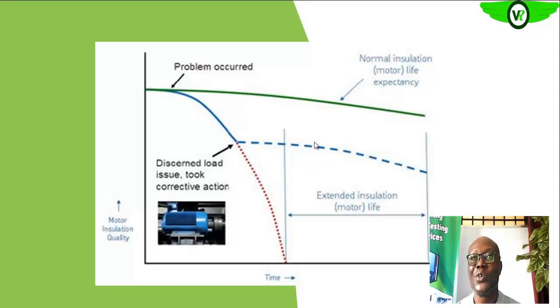So the beauty of this again is also that if there is no industry standard available to you, you already know the characteristics of that equipment from your previous tests and measurements. So when the equipment was working normally, you know its response to those tests. So when there are deviations, you also know, and those deviations are indications that something ugly is happening within